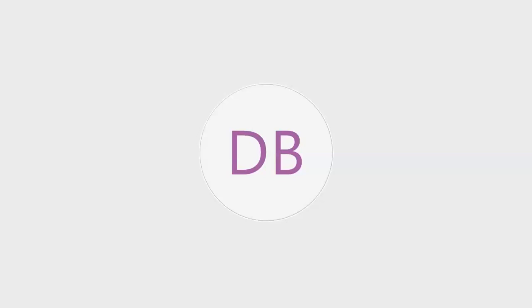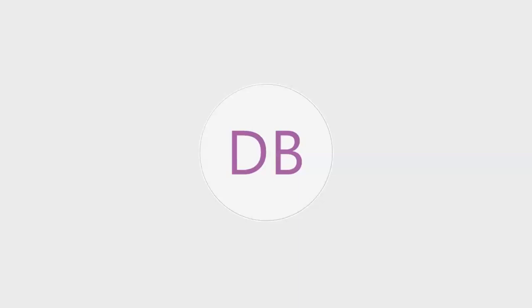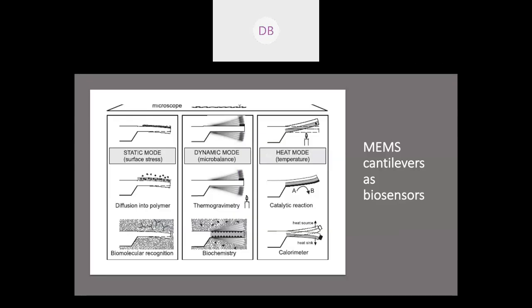But this is less used at a micro scale. Most of the applications that we find in the micro cantilevers are with a static mode and dynamic mode only. So generally we can ignore this heating. In the static mode, the surface stress plays a very important role. What is the stress that is induced into the cantilever, and to what extent? This stress is converted into piezo resistance, a very commonly used principle. That is where we can generate handheld devices, with a piezo resistive principle or a piezo resistive transduction process.